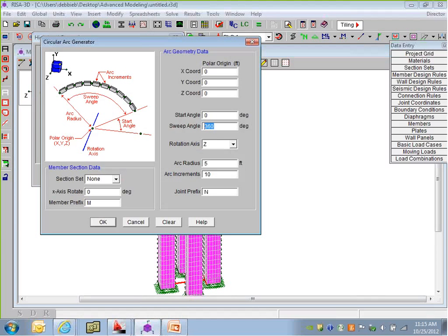Now it's asking me where to put this circle or this ring. What I want to do is put it around the origin, which is exactly what we just found, 19.5. The top of the location is 144 feet, we said originally that's the height of the tower, and then 4.5, that's the z-coordinate. So when we found that center point, that's these numbers.